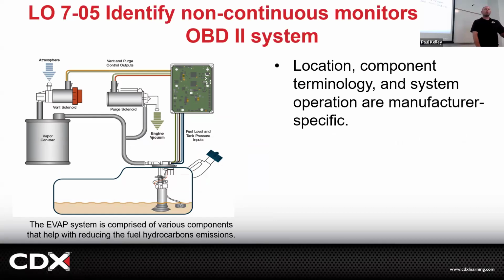They monitor it in several ways, but one of the ways they monitor it, we have a pressure sensor in here. And if you're going down the freeway and we close the vent solenoid, that means new air can't come in. And you don't purge it, that means no vapors coming out. And you run down the freeway, the fuel pump's sucking up gas, right? So that's gas levels going down. It wants to pull air in, but it can't. That's going to make a vacuum, like a suction, correct? Depending on how sealed the system is, it'll make a varying amount of suction.